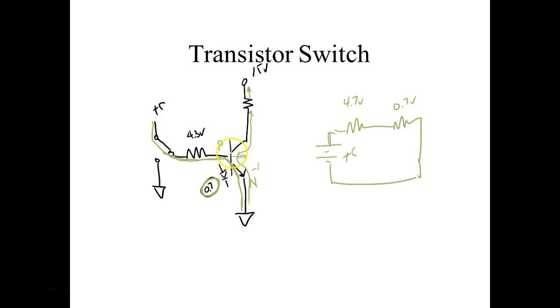What happens is that this base basically crams those electrons coming out of your emitter. It crams them into a spot, because not many of them can go out the base lead. And what are electrons looking for? They're looking for a positive. So if I put a big positive up there on the collector, what's that going to do? It's going to pull 99% of the electrons through there. So what we're saying is I might be providing 1 milliamp over here. Over here, I might be getting 100 milliamps of flow over there.